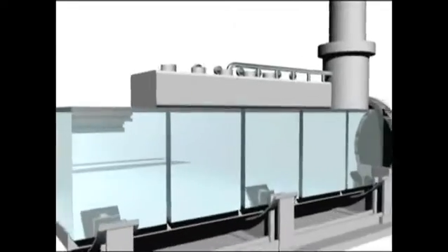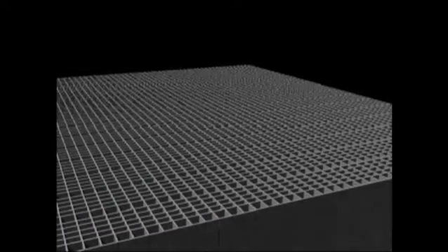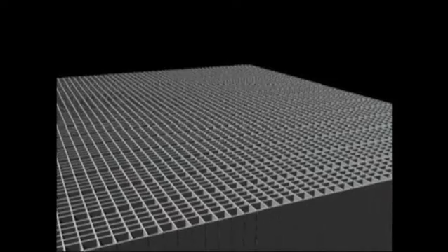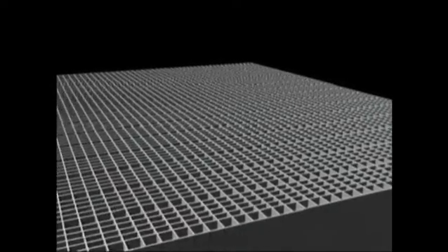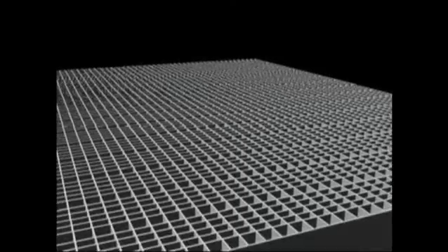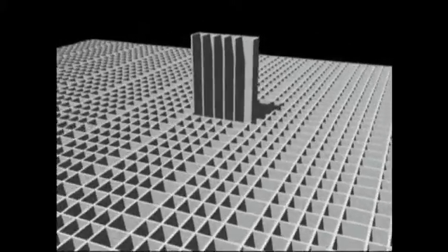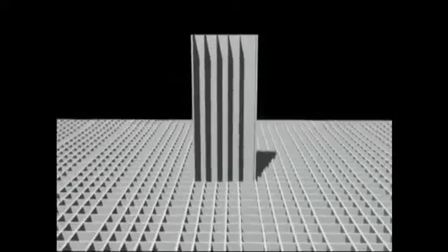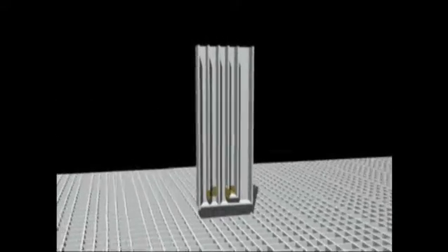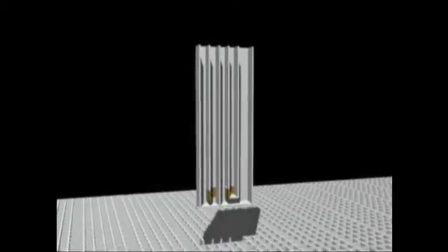gas produced. Inside each reactor block, proprietary manifolds uniformly distribute flow into thousands of microchannels. The architecture contains many identical repeating units, consisting of channels for each of the inputs, air, fuel, and reactants, and outputs, exhaust and synthesis gas. These channels form repeating layers within the steam methane reforming reactor blocks.